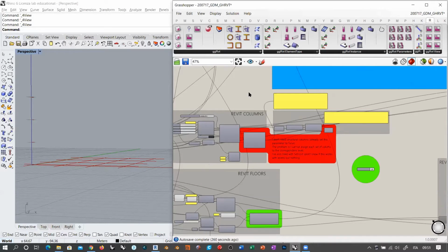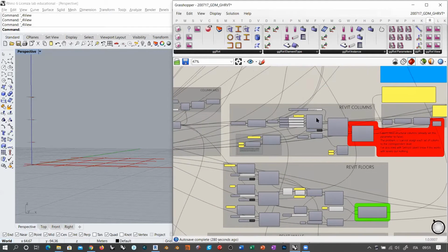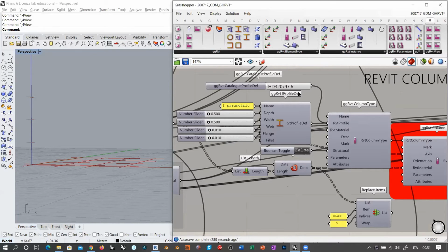And they also advertise that if you are using some particular structural calculation software, you can tell them, and they are going to also connect Rhino Grasshopper to that particular software via IFC. So it's pretty open as possibilities. But yes, that's the reason why you might want to define this profile by hand or with parameters.